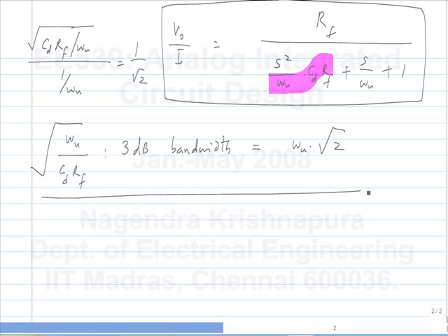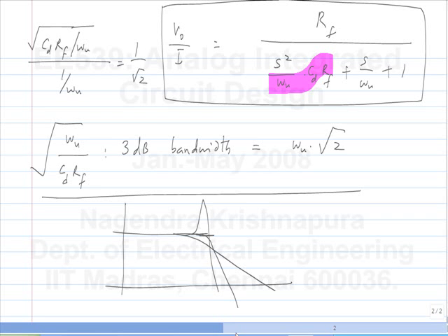So, without C, there is a first order roll off. Now, with C, you introduce extra phase lag in the feedback path. As you introduce more and more extra phase lag, the circuit tends to ring more and more. So, essentially what you are trying to do is to introduce a tendency to ring just beyond the bandwidth without the capacitor. So, it goes something like this. But of course, if you overdo it, you will get something of this sort. That corresponds to Q more than 1 over square root of 2. So, you adjust it so that there is no peaking in the magnitude response and go with it.